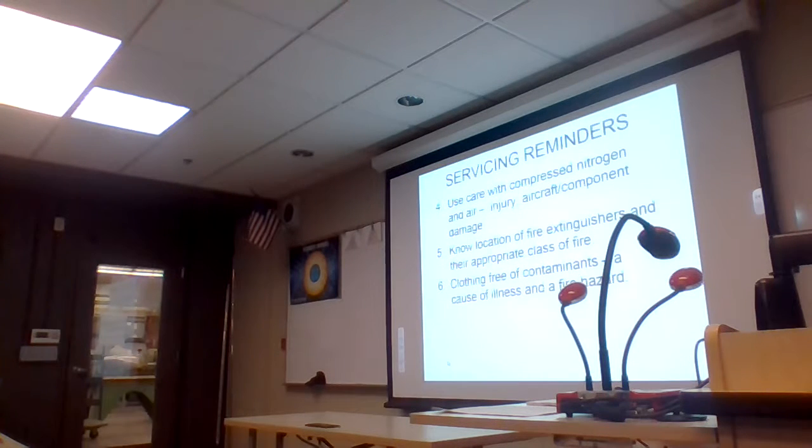They contain anti-wear additives. One of them is called TCP, tricresyl phosphate. It's an anti-wear additive in most of the hydraulic fluids, but sustained exposure to that can cause paralysis. So again, you don't want to walk around with it because of the chemical constituents of the hydraulic fluid, and also some of the fluids are flammable too.